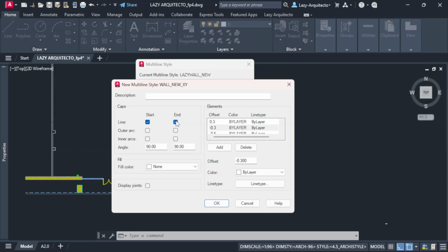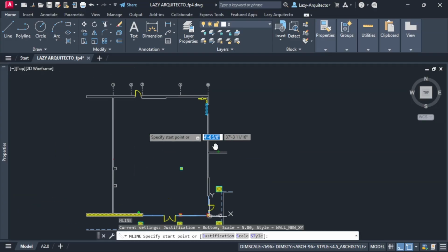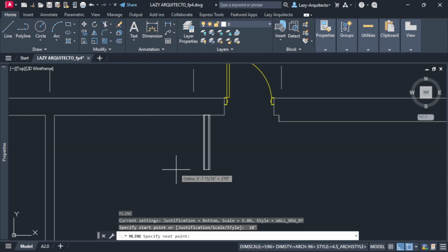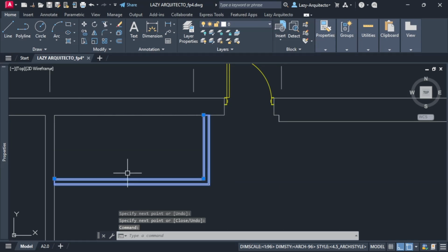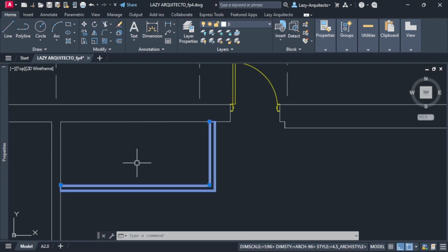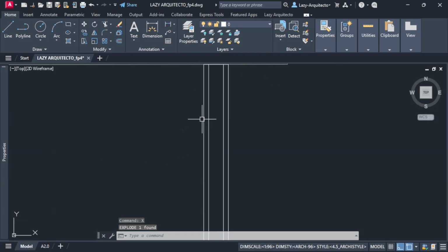or closed automatically. If I use the multi-line command with its shortcut ML to start creating my walls over here, I said I want 10 feet and go down. There are a couple of problems. It's coming as a block. We don't want this at the office because everyone uses our plans. I'll have to explode this, change some layers manually.